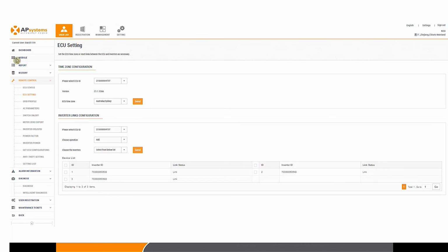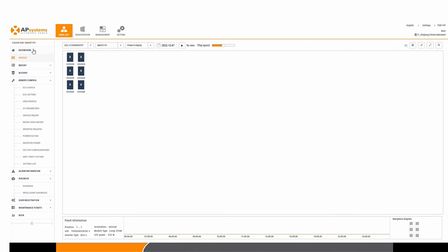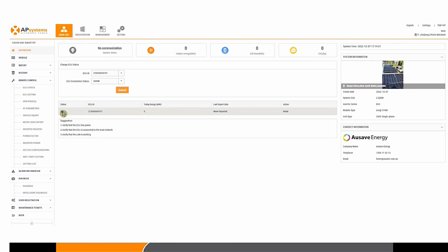Okay. So if you get a customer that just shows black, it means that the inverters is either the firmware is not updated or it's not connected to the internet yet. And these are usually quite common for newly installed jobs. So this job was installed on 12th of today, I think. So that's probably why. Most likely the ECU is not updated yet.